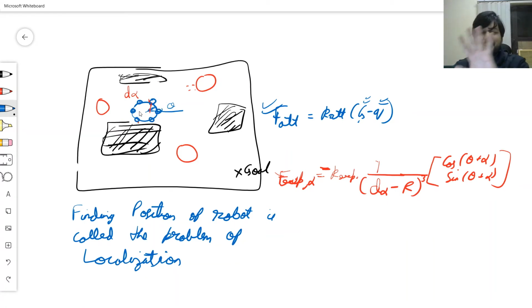That's very cheap. Everybody can afford it. You get rings of 8 sonar sensors, rings of 4 sonar sensors, rings of 16 sonar sensors. Beyond that, the radius of the robot does not allow. So it sends rays in these directions. Usually they are not mounted at the back. I've shown it at the back, for a different reason.